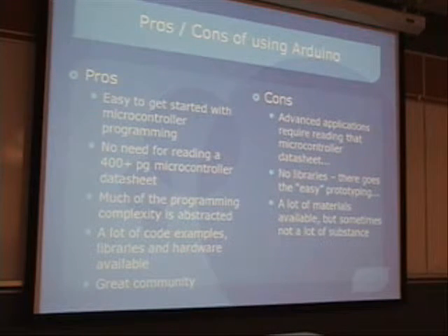However, there are some disadvantages to that as well. Advanced applications would require you to access everything just as you would in AVR Studio. So this is nice for someone who has never seen a microcontroller board before and wants to basically use a simplified version of C to do some simple stuff like blink LEDs or not so complicated applications. And when you actually want to do more, there's no direct way to do it here. You still have to use AVR Studio, or basically rely on your memory and import the regular libraries from AVR Studio within the Processing IDE.